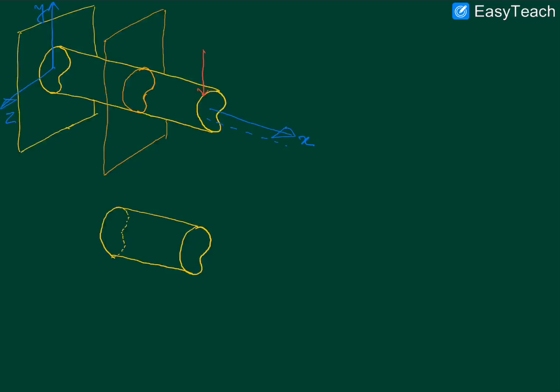Then the free body diagram for this cutout piece would involve this kind of transverse force definitely, but on the exposed surface, which I will represent by hatch here, which is hidden away behind, on that hatch surface there will be a distribution of stresses which would also be contributing to the torsional moment if we choose to take the torsional moment about any axis.